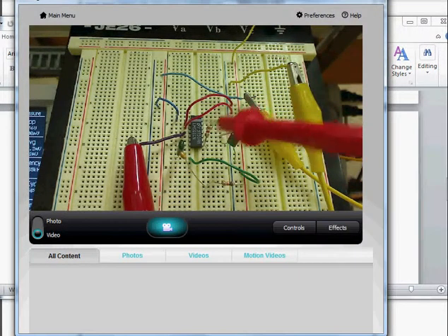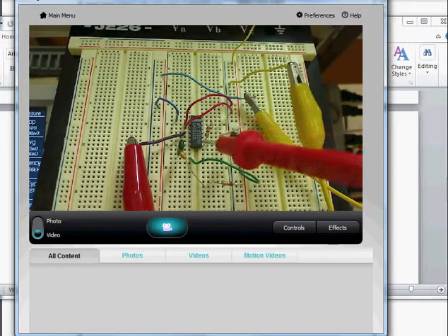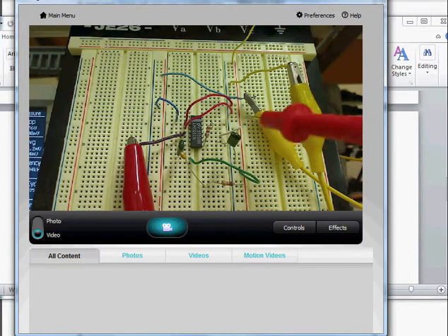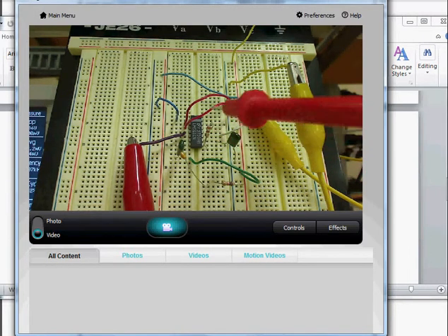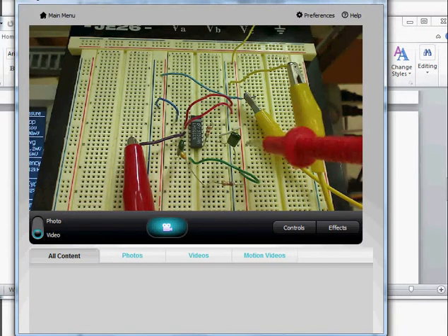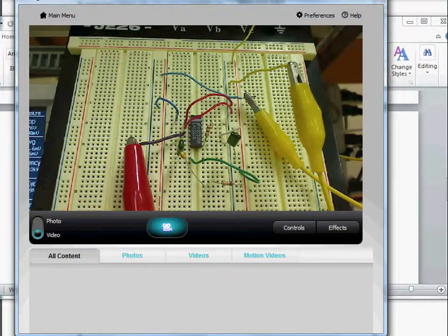For the connection at pin 8, we have a timing resistor, which is 3.9K. It connects with pin 10. Pin 10 is our positive power supply. And at pin 9, we connect a 1N capacitor to ground. So that is pretty much our circuit.